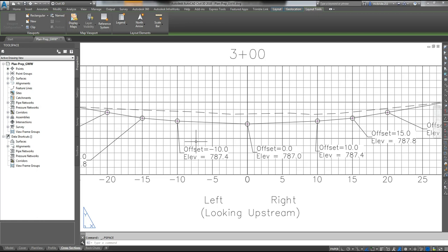But then to get the shape of the cross section, to make sure that the contractor is getting the proper parabolic shape, I can go out to my standard checkpoints, which is the standard 9-point checks. What that means is 7 points in the center of the waterway from edge to the inside, and then 2 points outside the grass waterway.